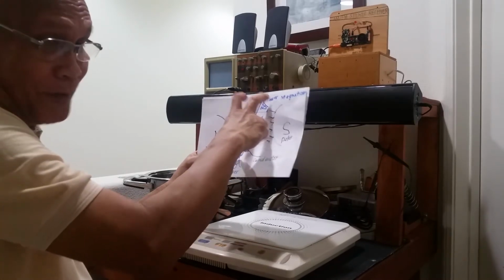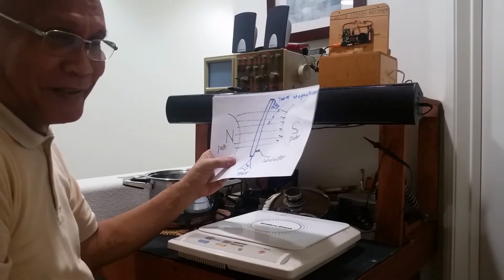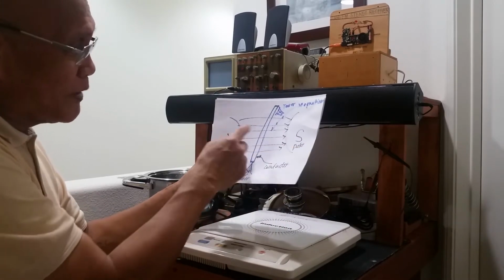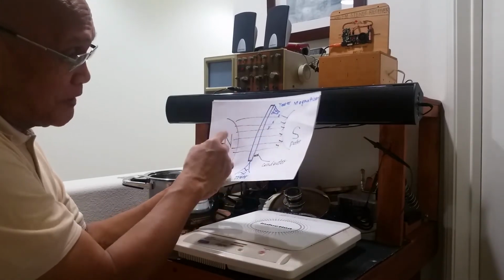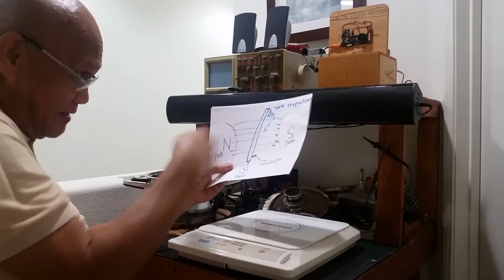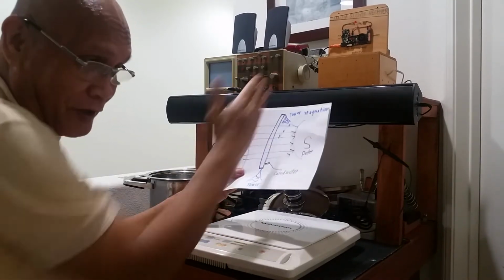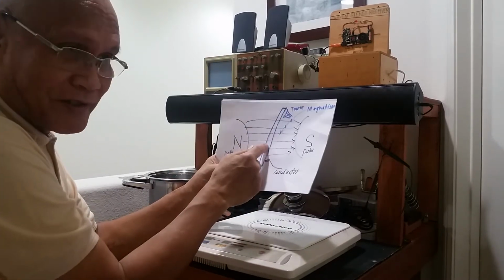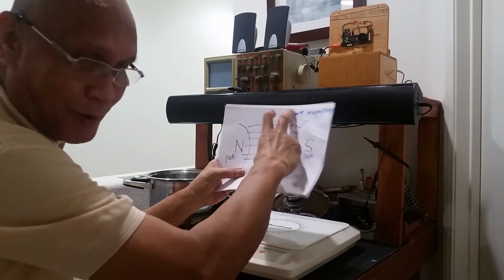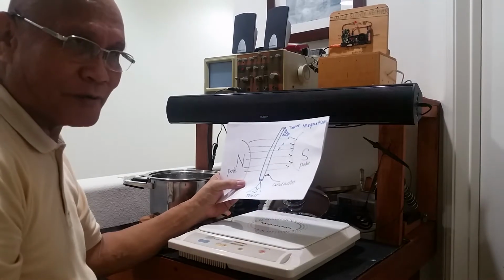That's the principle of a generator. The one moving is the magnetism, the flux of the earth. As it strikes a conductor placed perpendicular to it, it will induce a voltage. Whether we like it or not, if you put your voltmeter across this, there should be a voltage across it. It's alternating.